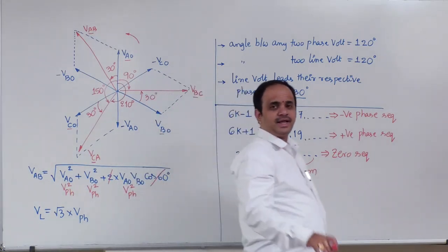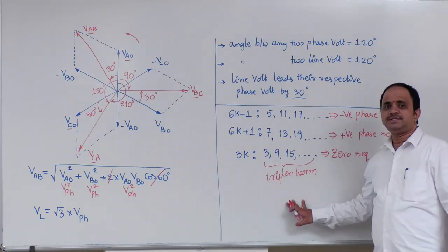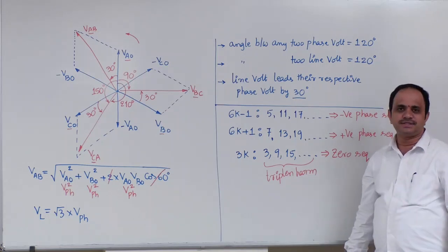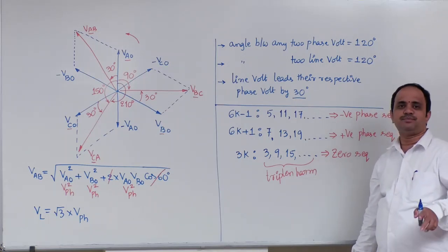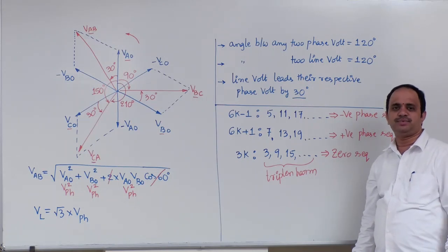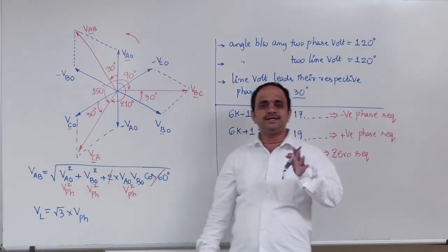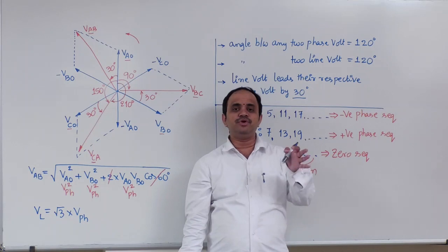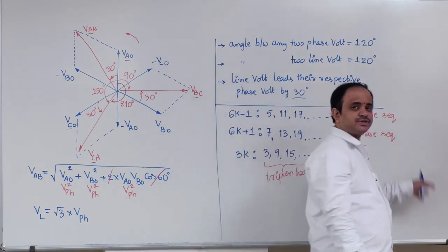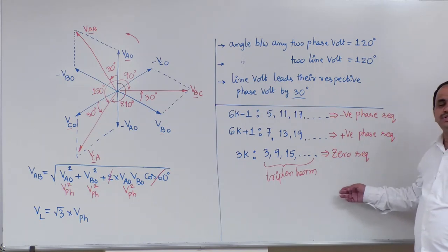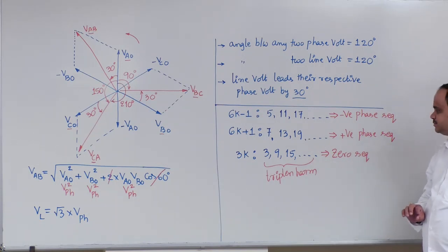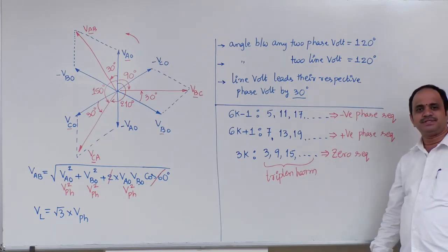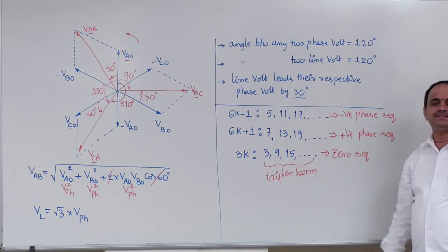In power system fault analysis, we will study that whenever the system deviates from balanced conditions, such systems, meaning unbalanced systems, will be studied with the sequence components: positive, negative and zero sequence components. Another reason, which is not discussed in the power systems course, is the effect of harmonics. Due to harmonics, these phase sequence components, positive, negative and zero sequence components, will come into the picture. When negative sequence components are present, what is the impact on system performance?